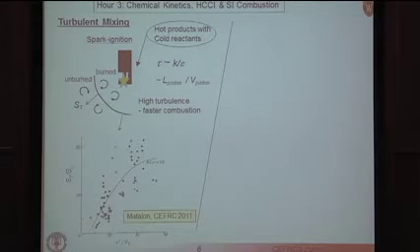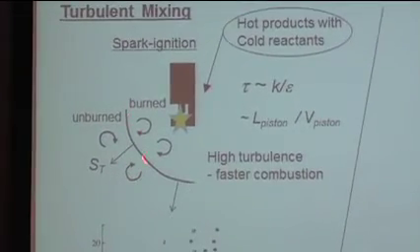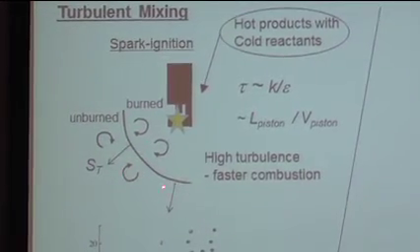So in response to your question earlier, this kind of summarizes what goes on. Here's your spark ignition engine. It's the mixing of the burnt gases and the unburnt gases that brings the burnt gases up to a temperature at which ignition is going to take place in a spark ignition flame front, a traveling wave flame front. The time scale of this mixing is determined by essentially parameters related to the engine size and the piston velocity. Piston velocity determines the turbulence intensity, if you like.